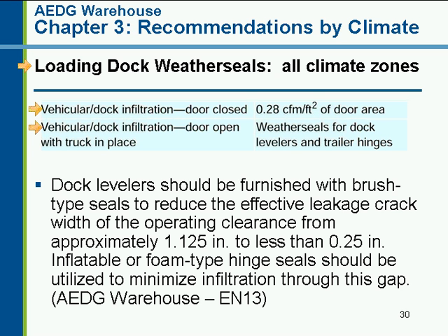When it's open and you've got a door in place, a truck in place, you want to make sure that there's a seal around the edge of that. So some sort of door leveler or some inflatable or foam type of seal so that you're minimizing infiltration in those gaps. And again, here if you go to the AEDG for warehouses and look at envelope tip number 13, it provides more detail on that.